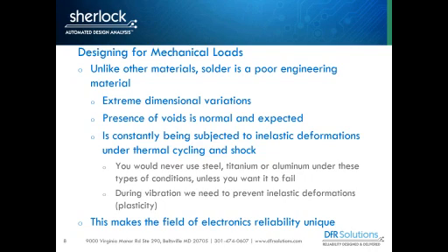But it still plays into the role during vibration. We need to prevent those types of inelastic deformations or plasticity during vibration events, really because of how rapid those types of events are. But again, because we're using this material in a regime that you don't normally use metals, it makes electronics reliability fairly unique in that regard. We're using a metal in a regime where a standard structural engineer would say, hey, you can't do that. Well, we have to do that in electronics.